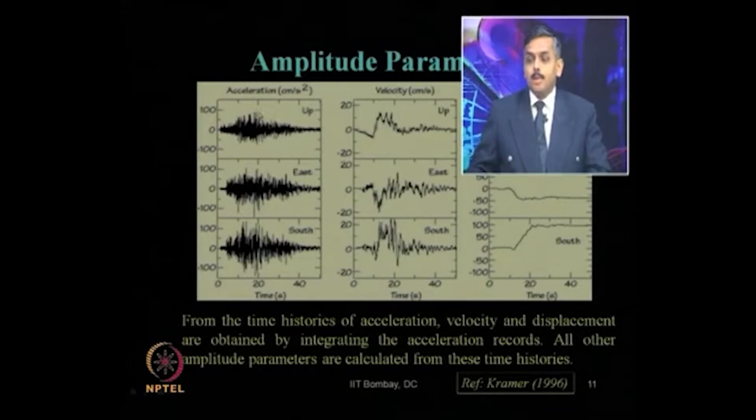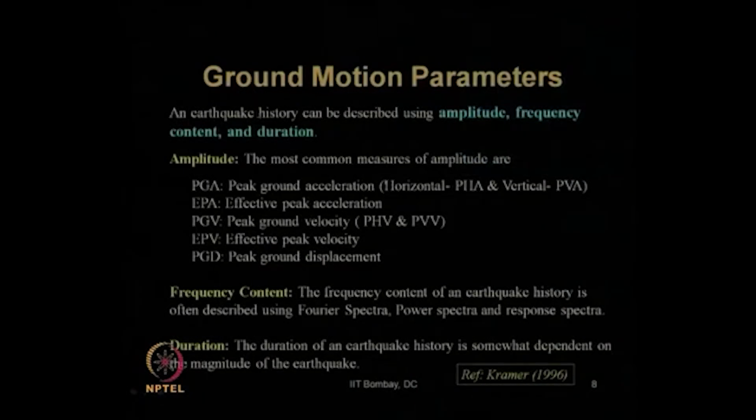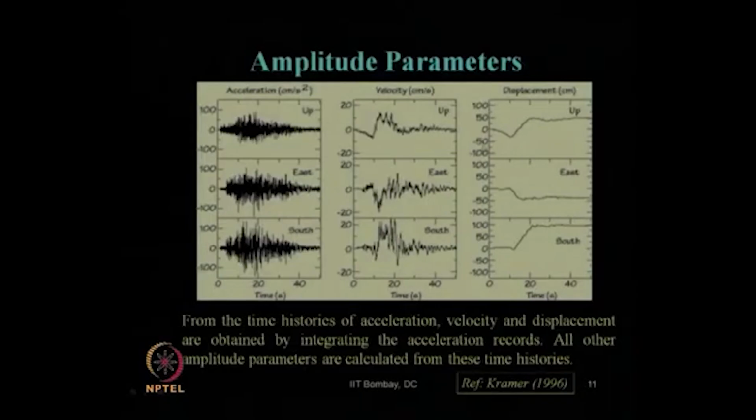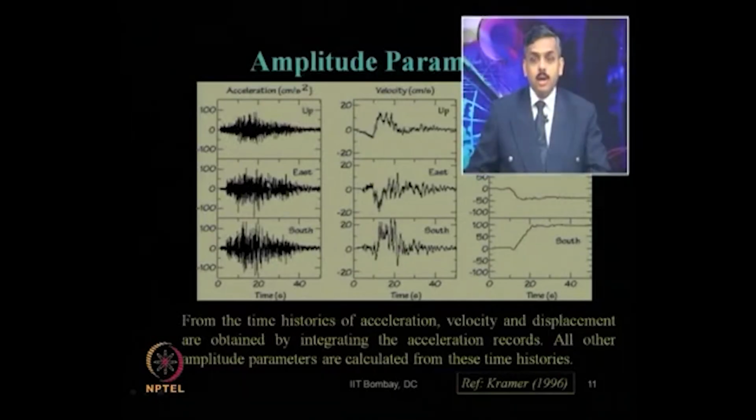And this gives you the maximum value of acceleration at ground level. It will be PGV, right? Sorry, it will be PGA, peak ground acceleration, but in the vertical direction. Am I right? So, it is basically PVA. Going back to the definitions we have seen, it is PVA, peak vertical acceleration. So, the highest value in this plot, whether you get it here or here, you need to take as the peak value of this vertical acceleration.